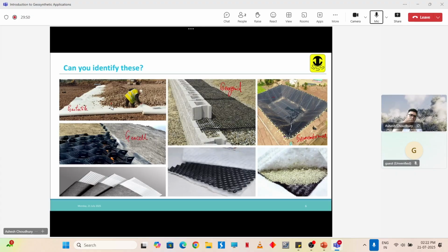Then here we have some corrugated sheet inside, and outside we are covering that with a geotextile. So these are long, flat, slender structures. We'll see that. So these are called PVDs, prefabricated vertical drains. Okay, let us come to this one.